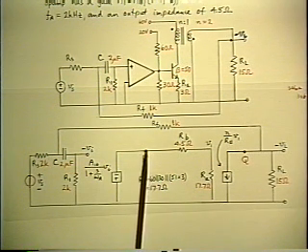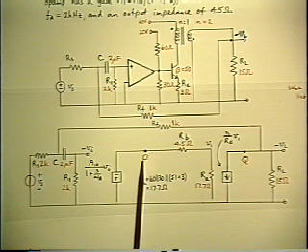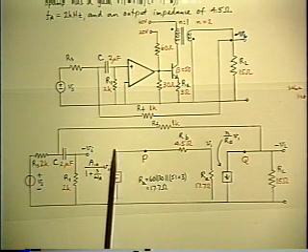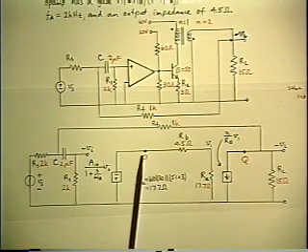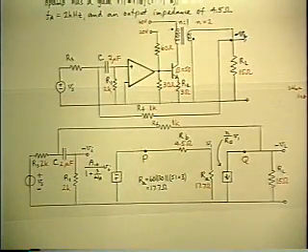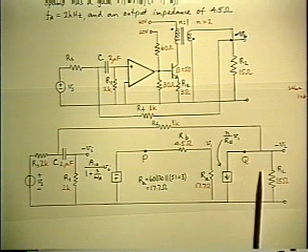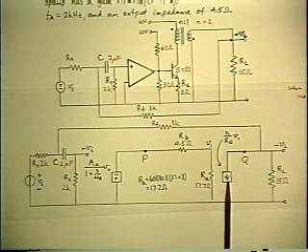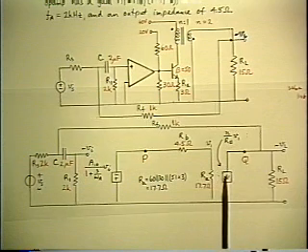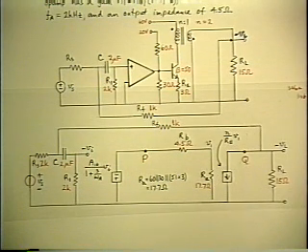And there are several possibilities. Point P satisfies the conditions for voltage injection because it's right after an ideal voltage generator. So we won't upset the loading if we inject the test signal at point P. So that's a possibility. Point Q is also a possibility. The opposite type. That would be okay for doing shunt current injection because it's right at the output of an ideal current generator with infinite impedance, so that's appropriate for shunt current injection. Either one of those would be all right. Can you see anywhere else you might do injection?